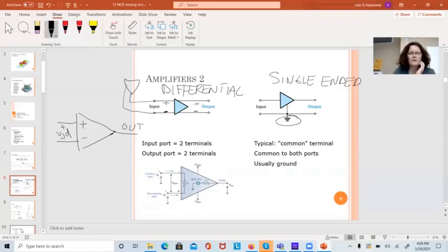The output's referenced to system ground, and it gets information about system ground by power supplies, V plus and V minus, and several of them, if they're precision op amps, will also have a pin that you have to drive to ground, so the device knows where your ground is. Now that's the model you looked at, and we looked at a really ideal model of an op amp in EE188. In reality, when you're dealing with these, you've got to think about a lot of things.